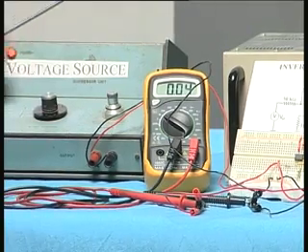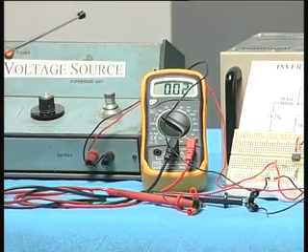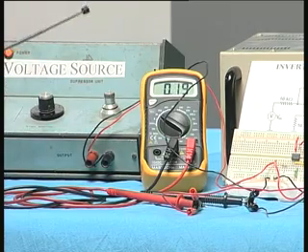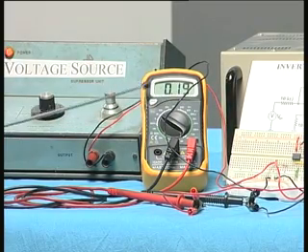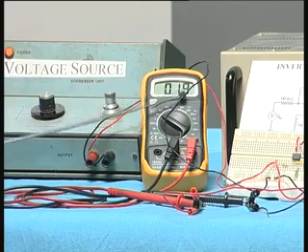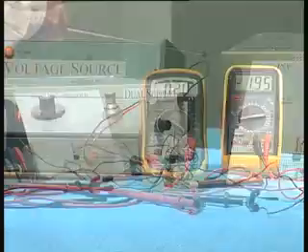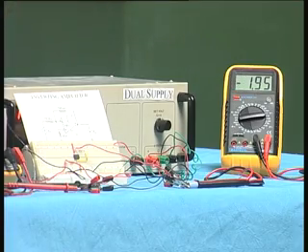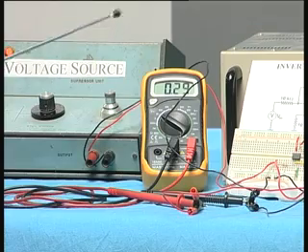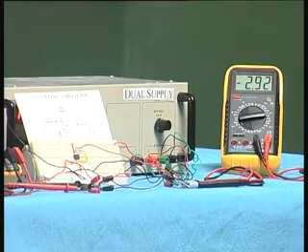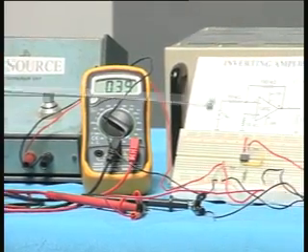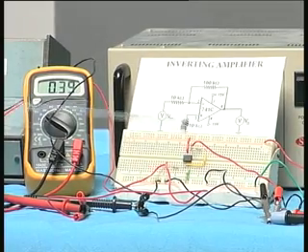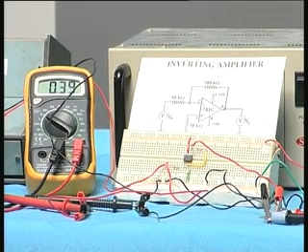Now if I keep on doing it, what I will do is I will increase it in hundreds. Now I increase to 100, so now it is in 2 position, that means 200 millivolts, that is shown as 0.19 or 0.2, right. So 200 millivolts multiplied by 10 should be 2 volts, that is why you are getting 1.95. Now if I change it to 300 millivolts I get 3 volts nearly. If I change it to 400 millivolt I get nearly 4 volts or 3.89. The difference, as you can see, is because the resistors are not precise. If I take 1% resistors for the 100k, 10k, etc., you would find it very close to the exact number.